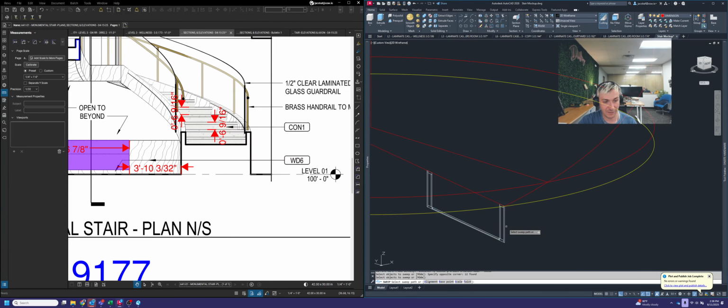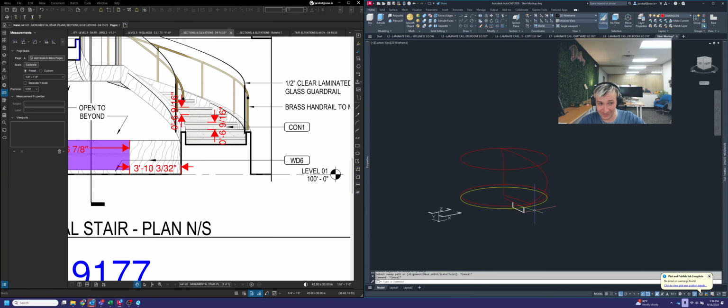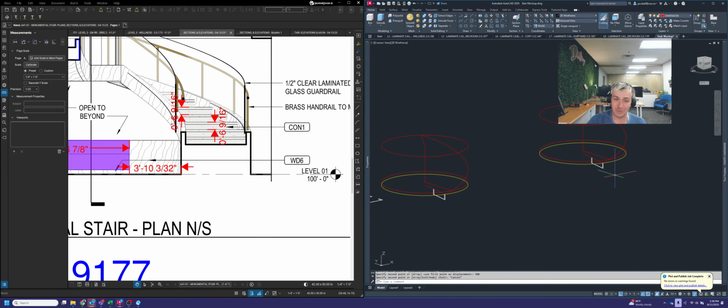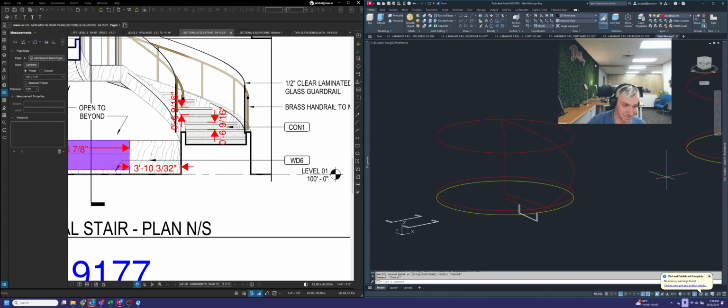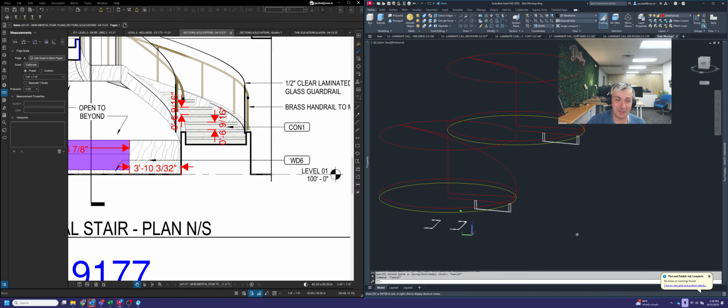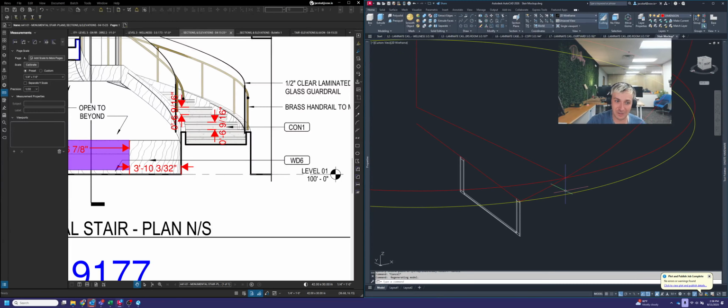Take that profile. Oh, and sorry, one more thing. I didn't even think about this, but anytime I'm doing one of these, I always save backup copies in my CAD file 100% of the time. If I ever get to a checkpoint, like video game terminology, and I'm about to sweep this, but as soon as I do, this helix disappears, what if I need it again later? So I'm going to save it over here.